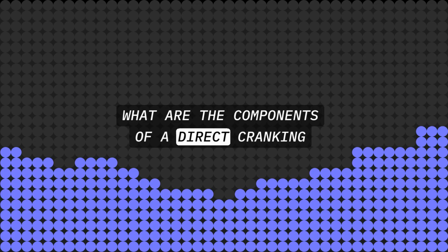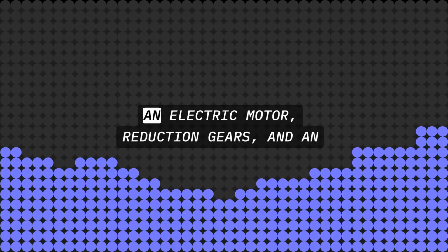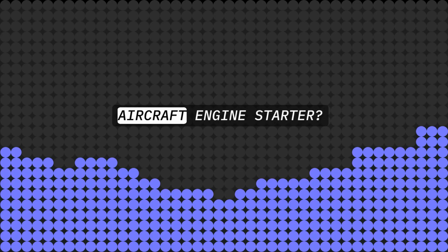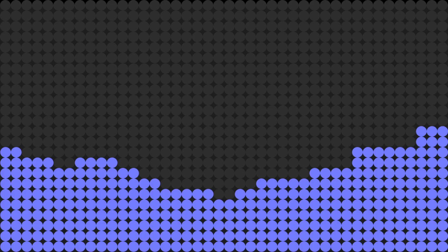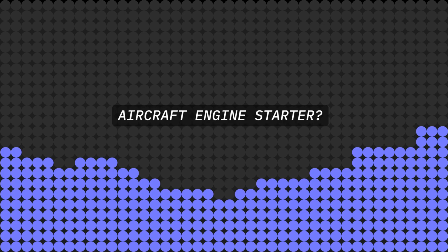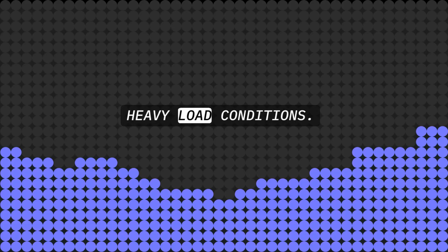What are the components of a direct cranking electrical starter system? An electric motor, reduction gears, and an automatic engaging and disengaging mechanism. What type of DC motor is commonly used for an aircraft engine starter? A series wound motor. Why is a series wound motor commonly used as an aircraft engine starter? Because it has high starting torque under heavy load conditions.